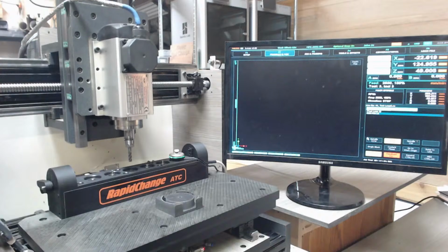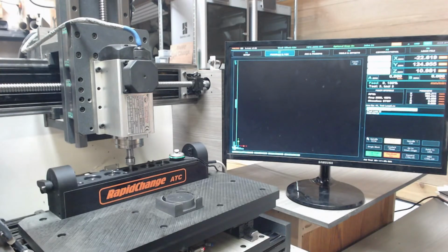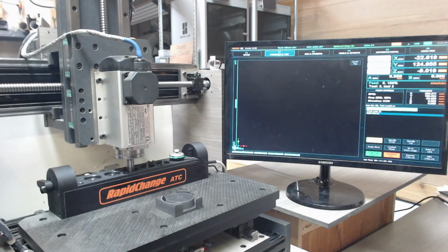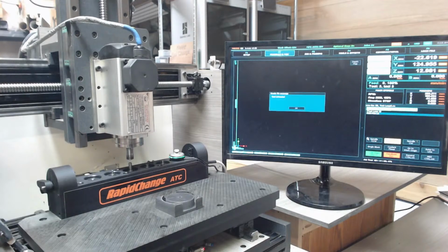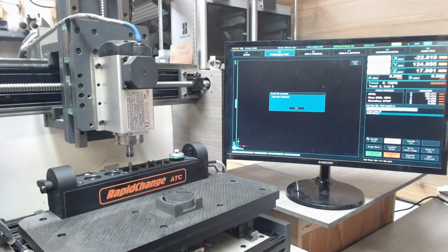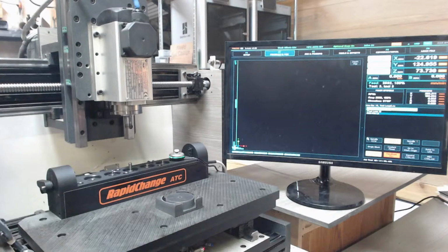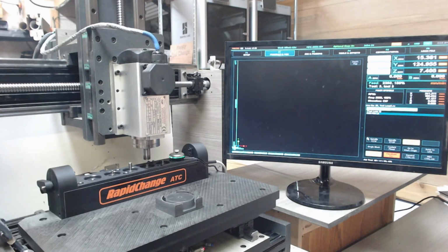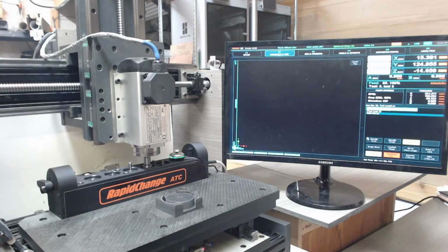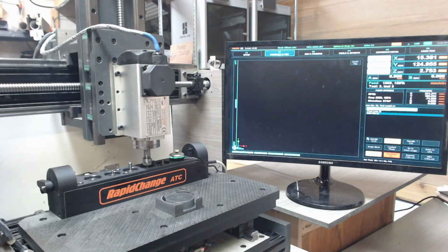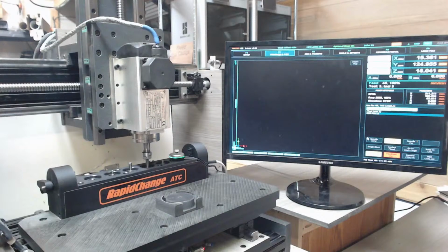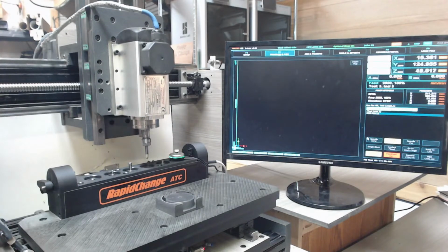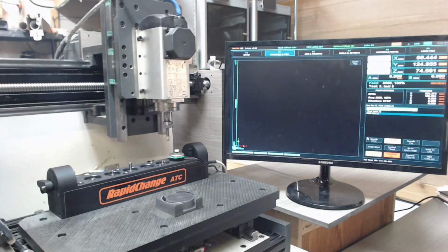Yeah, this one's actually got NEMA 23s. They're not super heavy duty. I think they're maybe 230 ounce NEMA 23s, but they're closed loop steppers, which is really nice. But the rack and pinion, I think that's really the fastest way to go. Some of them machines just fly.